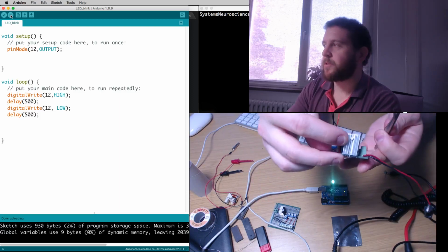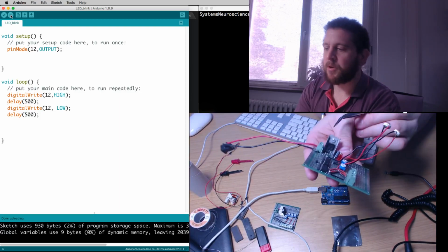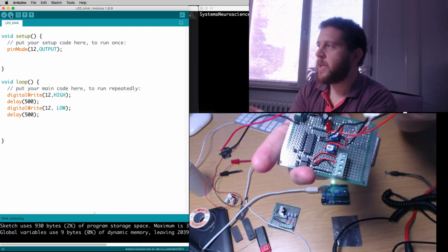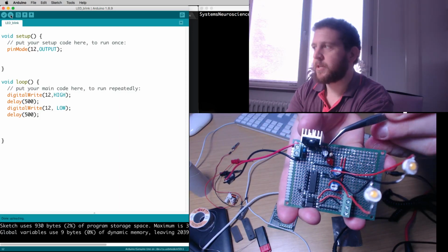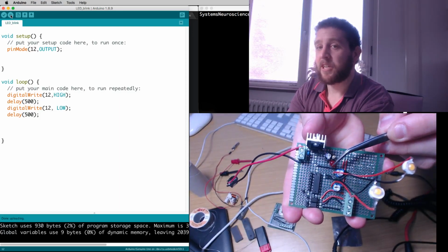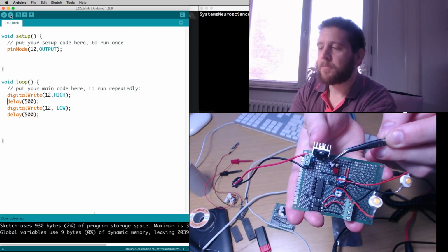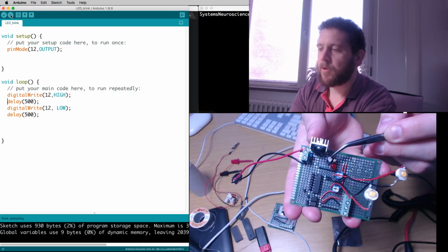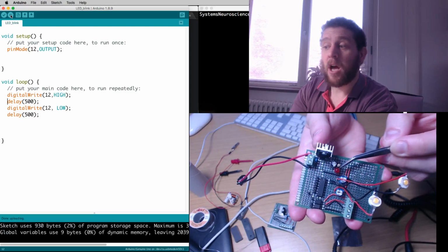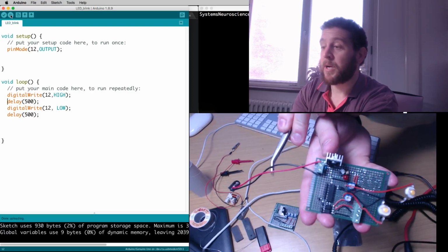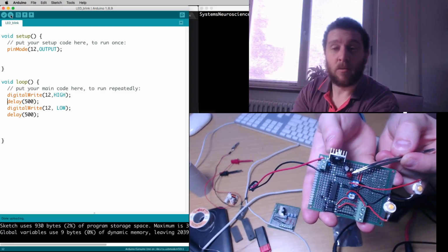That's why we've got this heat sink on the back. We're being quite gentle, though: it's only 12 volts in, 9 volts coming out. After the voltage regulator, we've got some circuitry, a capacitor and a resistor and an LED. This is smoothing the output of the power supply, so we've got a really nice, pretty stable 9 volts. I've got this red LED here because I want to make sure that when I've got 12 volts plugged in and everything's working, I can see what's going on.